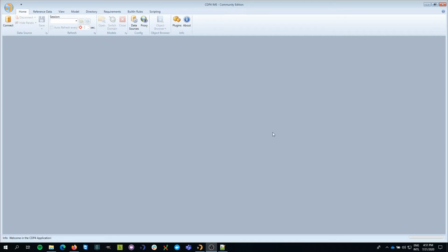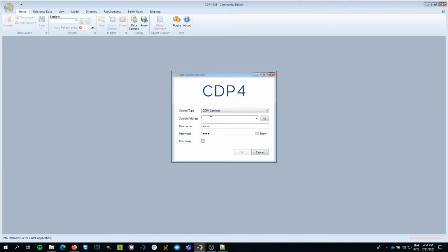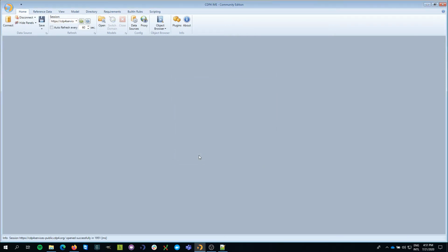Welcome to the third episode of the CDP4 video series, where I will show you how to create a new engineering model. So the first thing that we have to do, as ever, is connect to a CDP4 server. So I click on the connect button on the ribbon, I put the name of the server in and the username and password that everybody already knows.